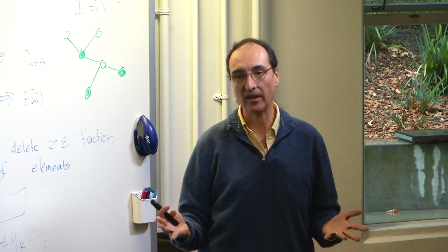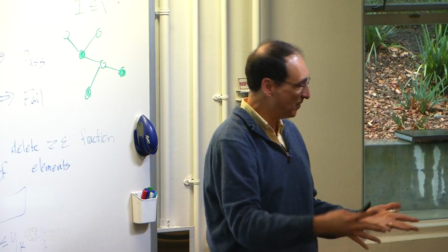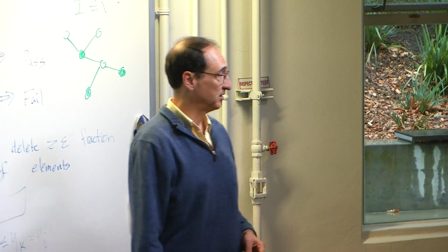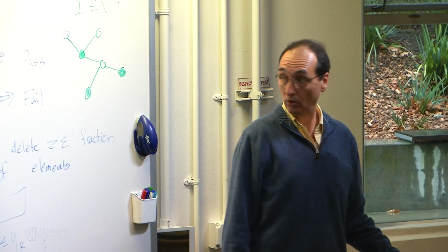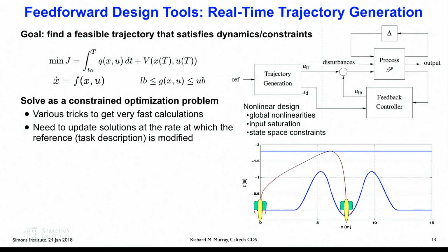So if you go look at an aircraft flight controller, this is what it's doing. It's generating the trajectory to come down and land, like the auto land system, and then it's regulating around that. It's got to stay in the center of the runway, got to come down at the right flight angle, all of that stuff, and it's doing these sorts of calculations on the inside. And so, for example, with this ducted fan that I showed you, the little flight control experiment, you might want to go from this position to this position. That's a person standing there, let's say. This is the roof, right? So I need to go from point A to point B in t seconds, while staying away from these obstacles or something like that. That would be the typical problem that you solve.